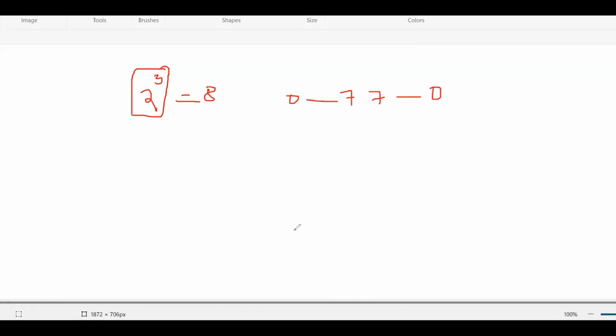If you take the modulo counter, we'll discuss it later. So here, for up counting and down counting, we should have two enables. Based on the enable, if up equals 1, it will count up. If down equals 1, it will count down. So we'll have the count up enable and the count down enable.